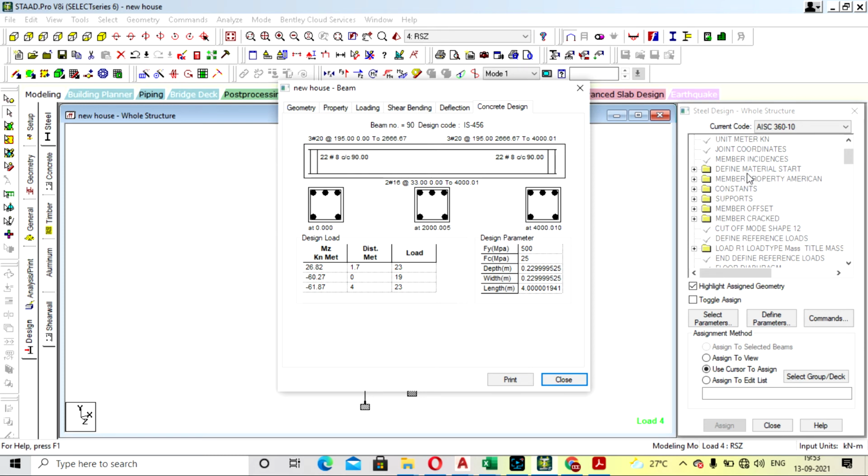So that was also economical for you, because 40 or 20 or 30 mm bars are generally not seen in normal buildings, G+2 or G+3 buildings. Up to 16 they will carry. And it was easier to get available also. So you can make that also.